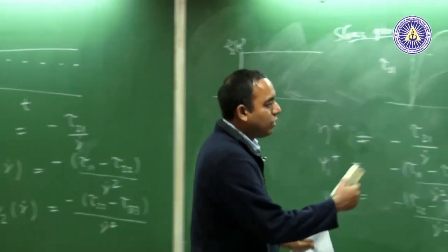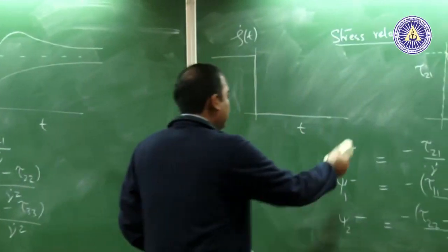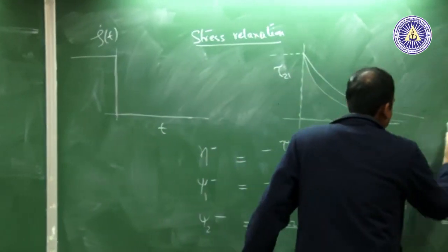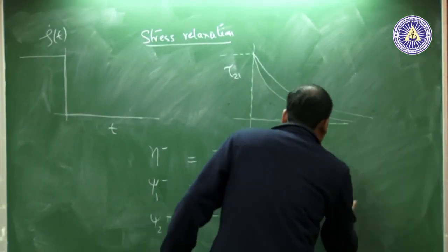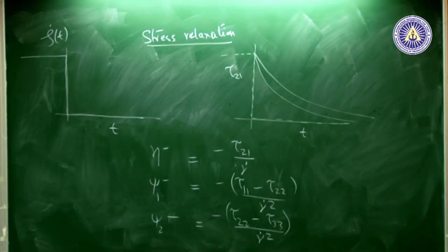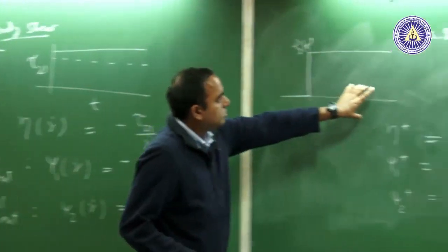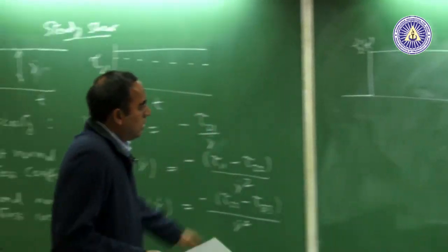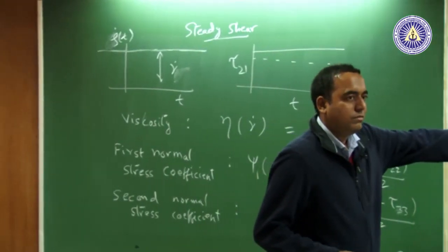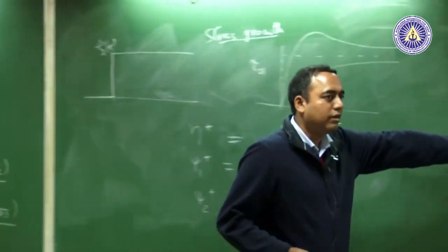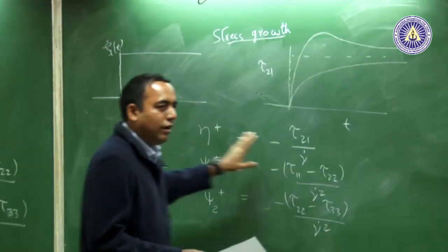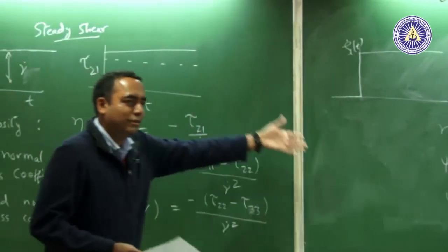Now, I will talk about models one by one, which explain some features of the data, and then we move on in terms of families. But the basic picture is, what I am after are models which can capture the experiments in terms of steady shear, and then these transient experiments in terms of growth and relaxation, and what I have not talked about is similar experiments done with extensional flows. There is only the family of shear standard flows that I have, and the material functions for shear standard flows that I have. An equivalent family exists in terms of elongational flows.